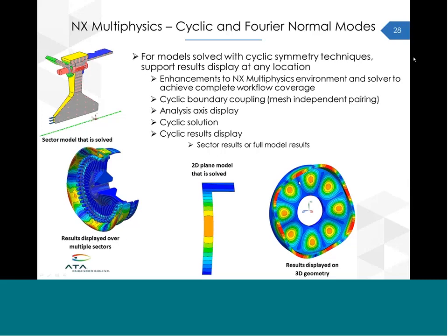The result you get actually accounts for some non-symmetric modes of the structure, or a mode that you would not necessarily be able to get if all you had analyzed was just this 2D sliver in isolation. So the software is able to look at this 2D sliver and understand how the mode shape should evolve or progress when you look 360 degrees around a circular structure.